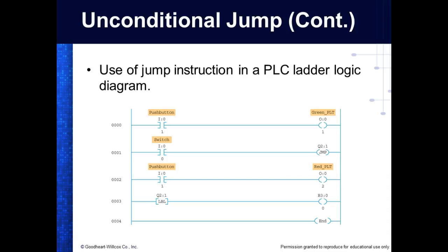So the example they give that they're calling unconditional is not truly unconditional, because, why? You're pushing a button. So it is making a decision, if the button is pressed or not pressed. When I look at unconditional jump instructions, in my opinion, since I've been programming for years, it means it will always jump. So in robotics, if you want the program to always repeat, you'd use a jump instruction.